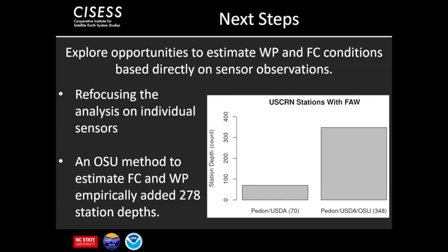Another thing that I noticed, especially when we are relating soil moisture to drought with the fractional available water, was that the wilting point that comes from this legacy information is typically overestimated. So what that does in the field, the soil moisture can go much lower. So now when you're using those overestimated wilting points, you are overestimating the severity of the soil stress as well. Is there a signature or something relevant that you have seen which gives that kind of thing even at USCRN sites?